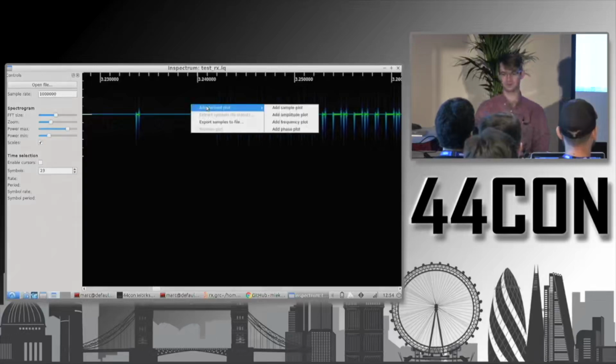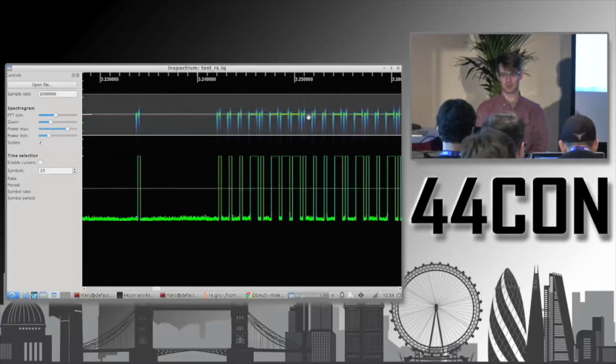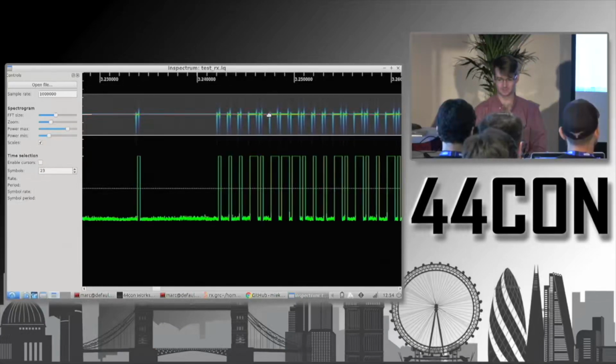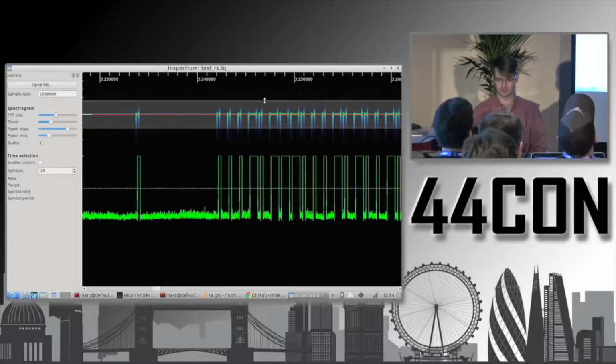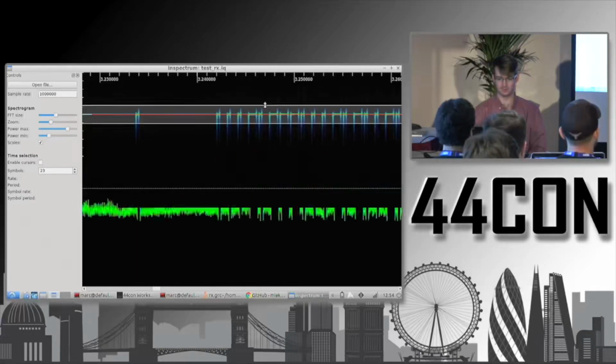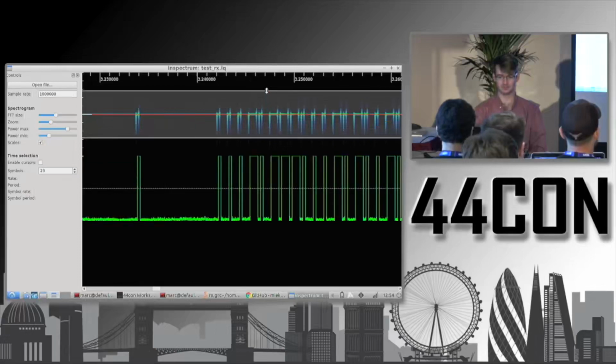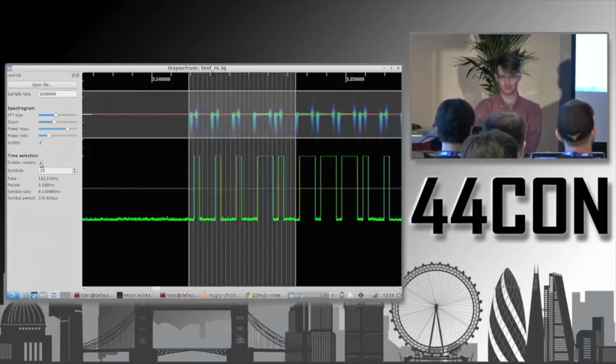And then one of the neat features is you can add this derived amplitude plot. And again, amplitude because it's an amplitude-based modulation. If it was FSK, you'd do a frequency-based demod. Drop on that plot, set up the parameters nicely here, and you just kind of have to play with the outer bars until the demodulated signal on the bottom looks right, namely until you have those really clean rising edge and falling edge on the data that you're looking for.